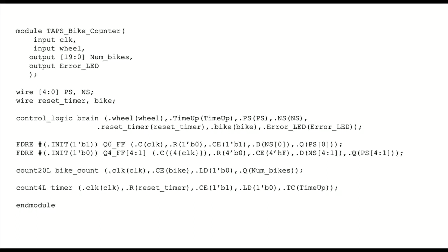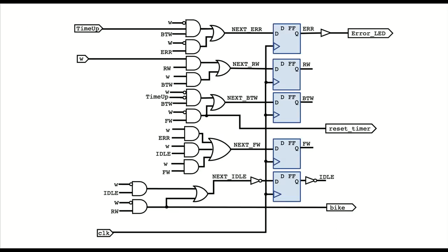But it's important that you think about blocks in Verilog, because one of the things that happens is it looks like code, and you think of it as being executed and running and producing values. But really what running this code does is it creates that. It just makes flip-flops and gates and connects them all.